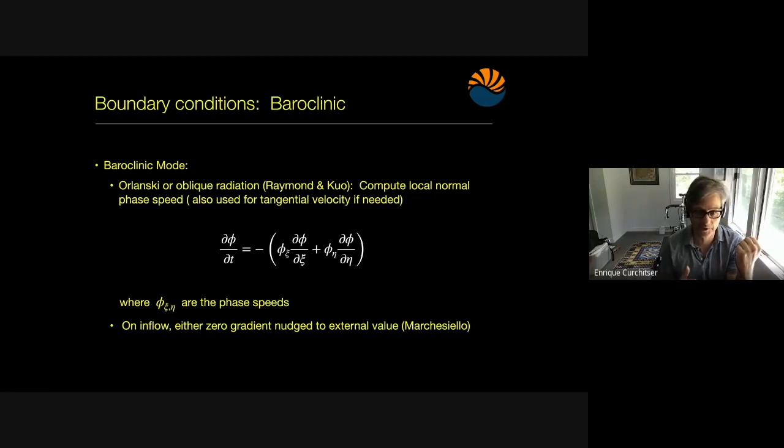But if you have waves that are, for example, leaving your domain, you can set it to a year or 300 days or whatever makes sense for that particular application. Basically, it gives you two tunable knobs that you can use to work the boundary conditions to look as best as they can for each particular implementation. There really is no canonical value that you can use for this.